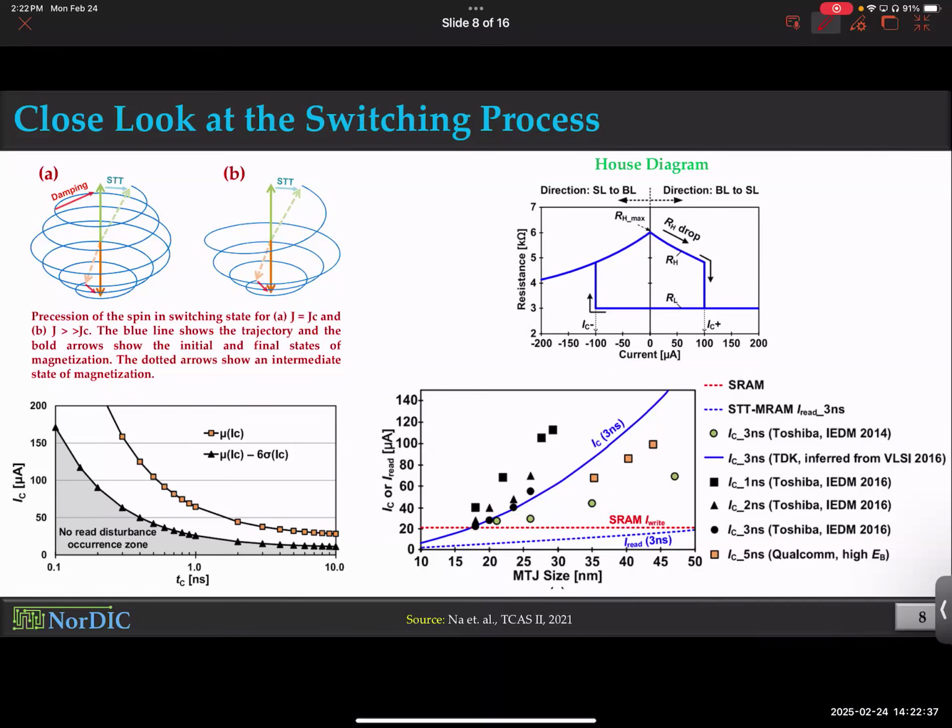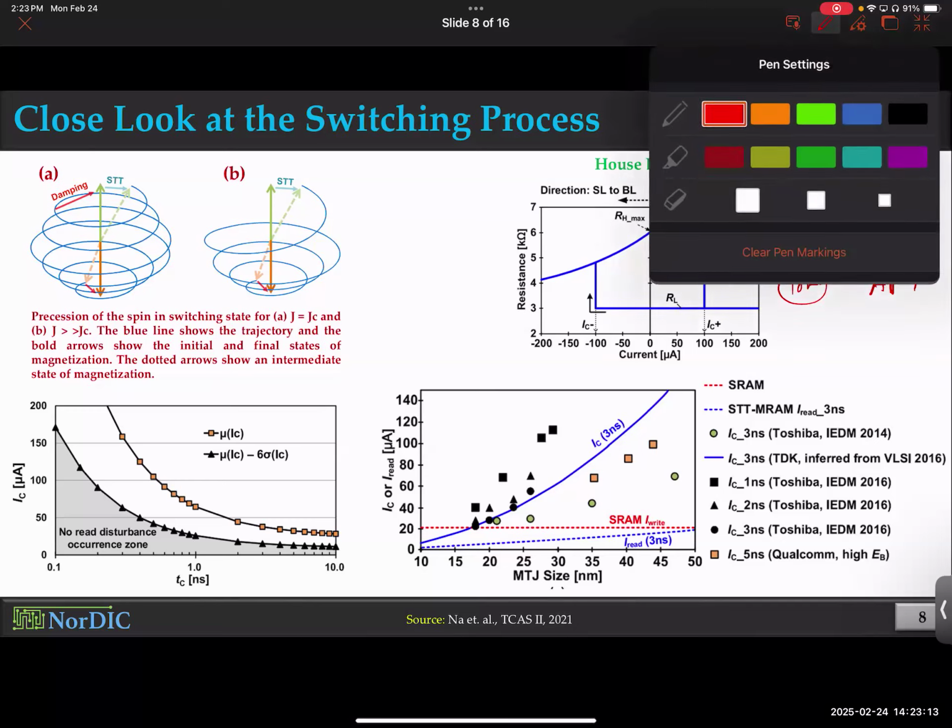Remember, I have been telling you that, hey, when a magnetic tunnel junction is in parallel state, RP, anti-parallel, RAP. And RAP is higher, RP is lower. We have been mentioning that as if it's a number. Maybe this is 1 kilo ohm, this is 10 kilo ohm, as if it's a constant number. It is not. Interestingly, magnetic tunnel junctions tend to be highly non-linear devices. Their resistance is also a function of voltage. It's not a constant resistance, like 10 ohm, 20 ohm. You don't get a constant resistance. So this is what you get.